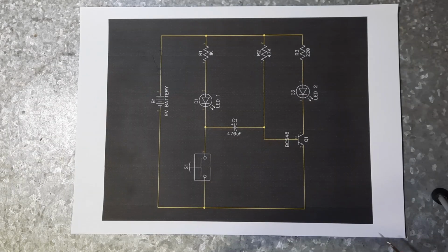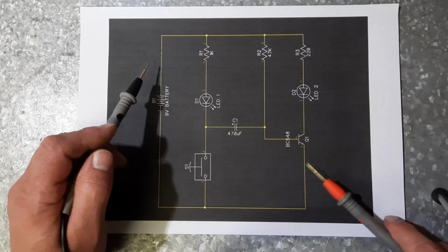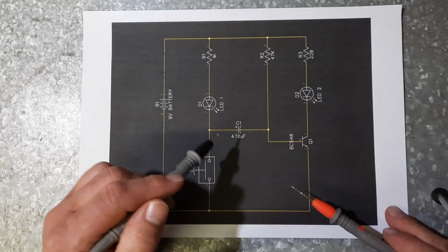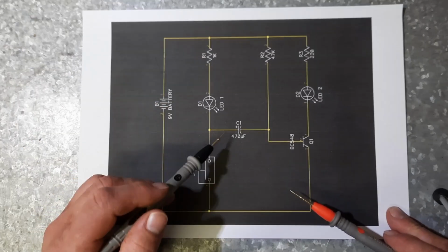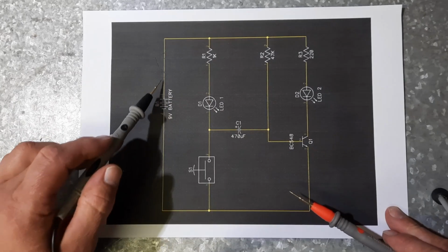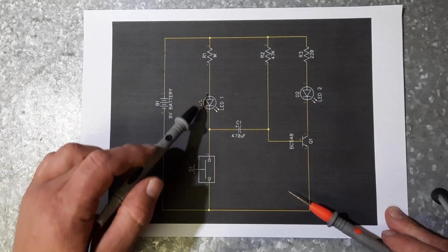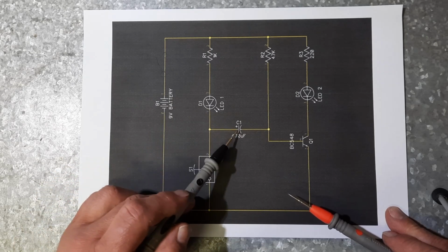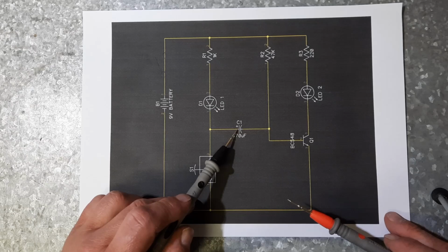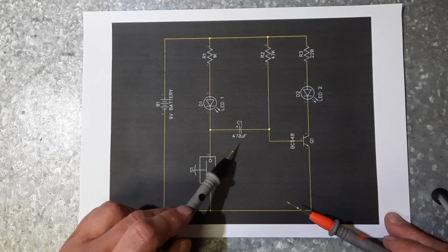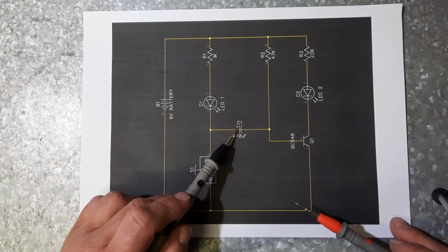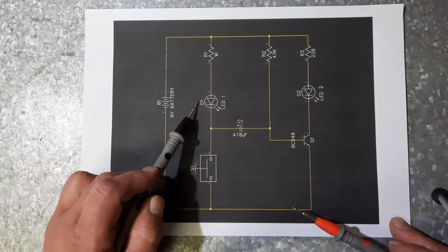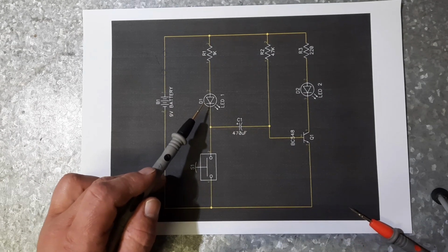So when we turn this circuit on, when we close this switch, this capacitor, while it's discharged, is going to look like a short circuit to these 2 components. So when we turn this on, current is going to also flow from here down to here and into the capacitor. The capacitor is like an empty tank. It is now filling up. So this capacitor started discharged, it's now charging. It hasn't charged fully yet, it's charging. While it's doing that, this LED is going to glow. So this LED will be on.